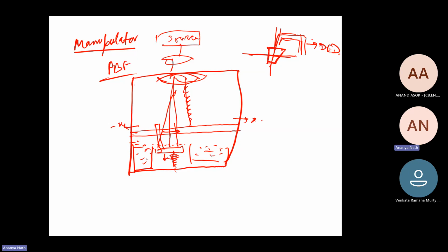This chamber will be fully controlled, with a controlled atmosphere and controlled atmospheric pressure. The oxygen will be 0 ppm at the time of printing to avoid oxidation in the printed part.